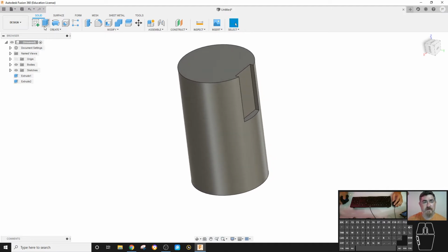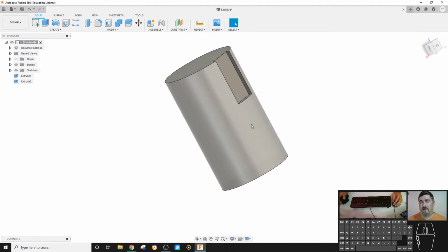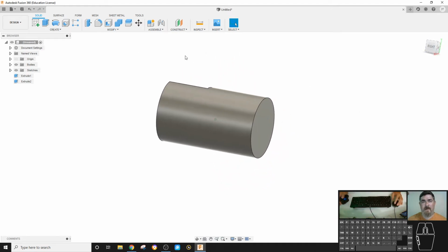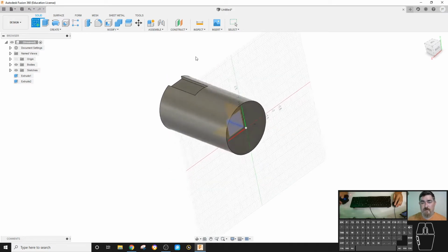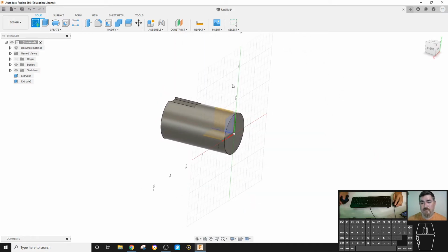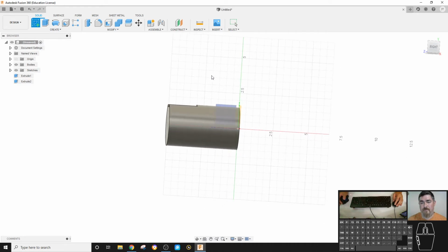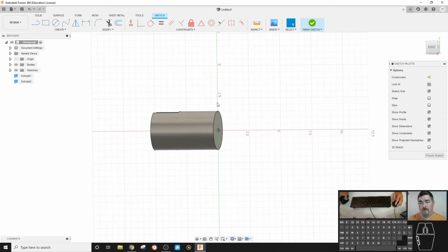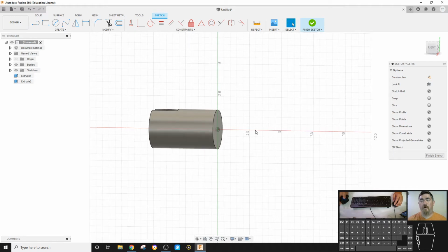So that's creating a sketch in Extrude. But let's say now I want to make a larger diameter, and it's going to be like a V. So I can create a sketch, and so I can go here and sketch on that middle section of the cylinder. And I want to make like a V shape. I'm going to go up a little bit, come down, go up, and so it'll have like a pulley or something.